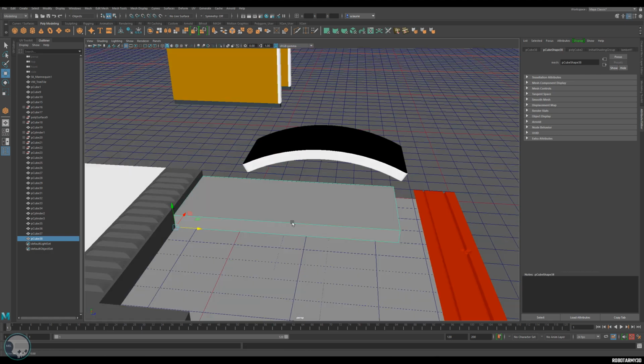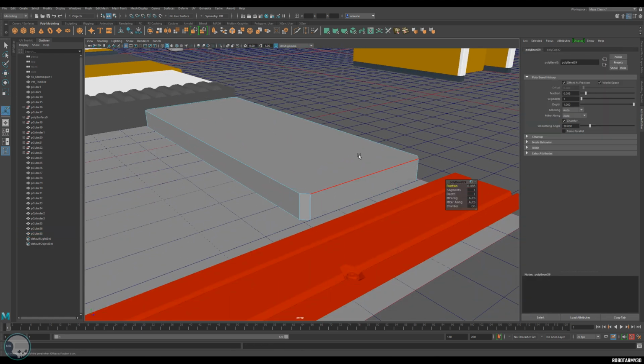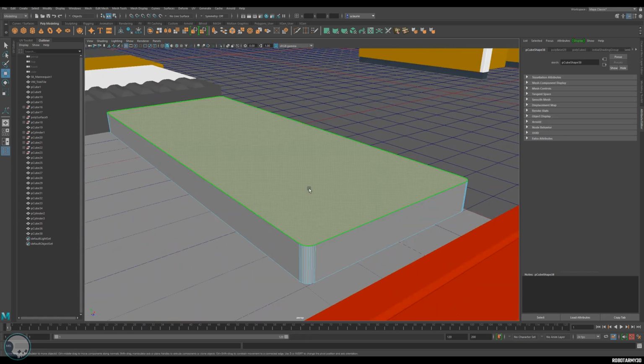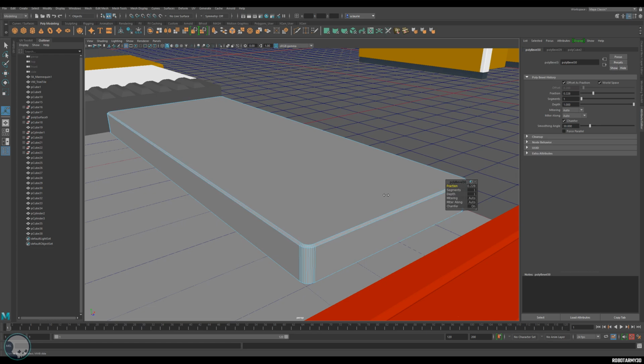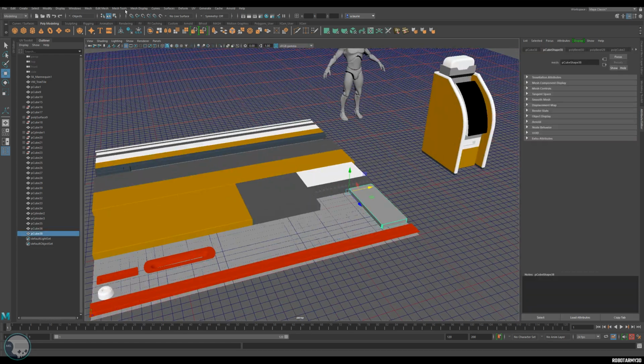And this is only going to be the glass, but it does have a nice rounded edge. So I'm going to put a bevel in this. And then I'm also going to just give the entire outer side a little bevel as well, so that we can get that nice chiseled look to the edge of that glass like you get on some mobile phones.